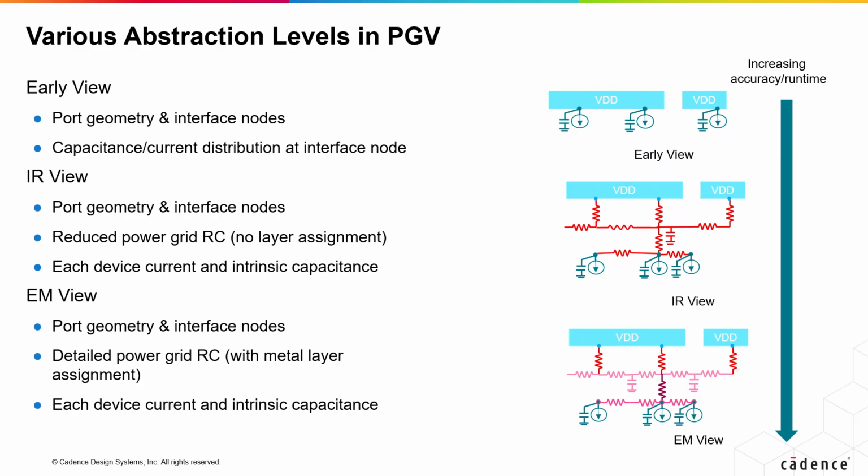For macros, it contains the extracted power grid from the GDS2 data of the cell. GDS2 and XY SPICE netlist is required to generate the accurate current distribution and decoupling capacitance. It creates current taps on the bottom conducting layer, at the location of the vias layer above it. The rightmost arrow shows different view types and the accuracy level. As we can see, the EM view is the most accurate since it contains a detailed RC network information.